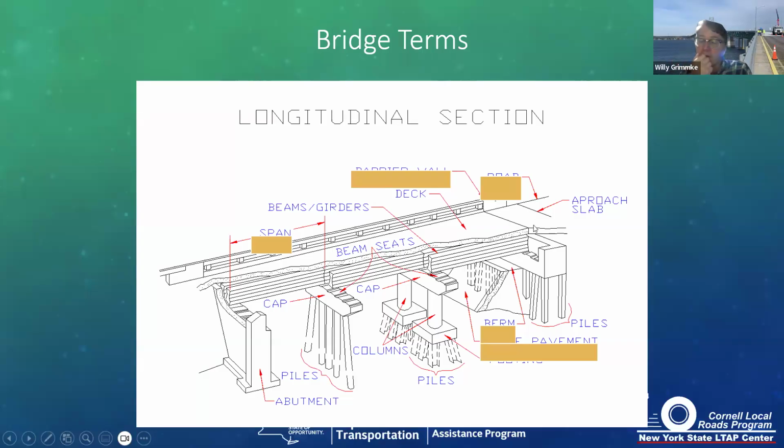Many bridges have an approach slab, which basically spans from the back wall back to the abutment. A number of local bridges and some states like Maryland don't often have an approach slab. And in the absence of an approach slab, you will know when you get to where the bridge begins, because there is often a little bit of settlement right behind the abutment.